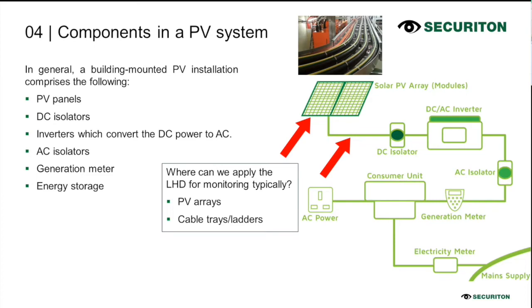So it is easier to maintain if it's below the panels. So easy access is possible, the first thing. Second, we do not need to be on top to capture the fire. We have the protection around the cable, which can also penetrate below as well. So it is not necessary to install on top of the panel and make it difficult for them to do maintenance.